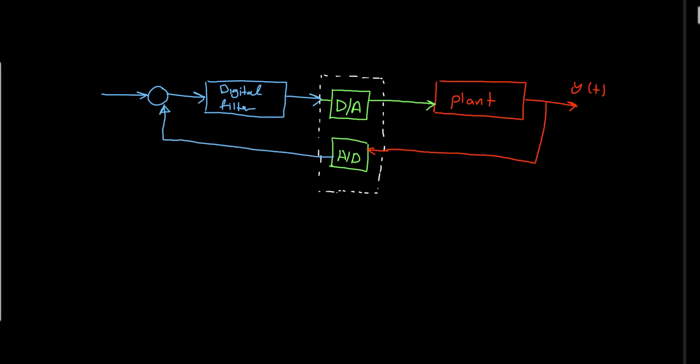Now I can complete my block diagram. So here I can assume this is R of K, let's say Y of K. Here I'm having U of K, and this will be U of t, and here is E of K, which is a discrete time system. So this part of the block diagram is implemented in a digital platform or inside, let's say, a computer.